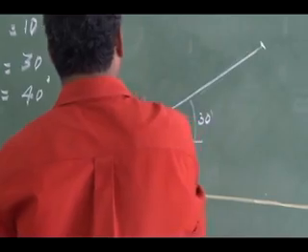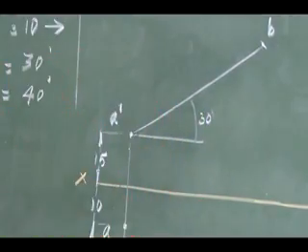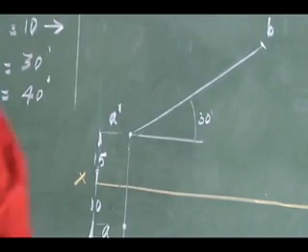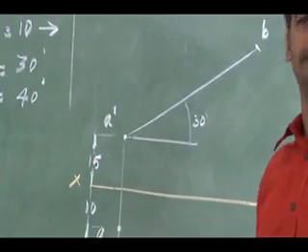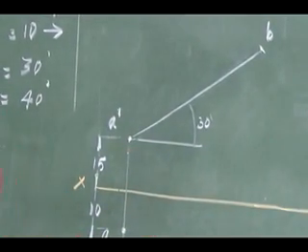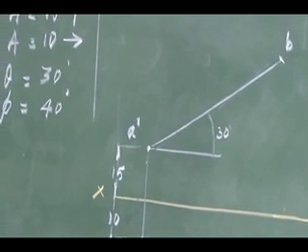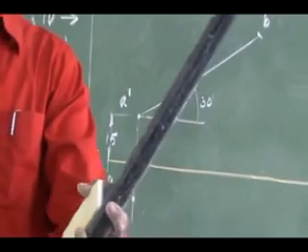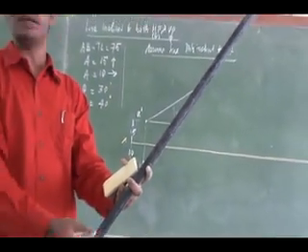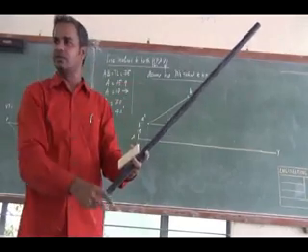So this is the location. Normally for a separate problem, I would notate the other end. Now I am assuming that I know one end's projection, and in this assumption that end location is kept fixed. I am assuming the line is only inclined to HP and parallel to VP.